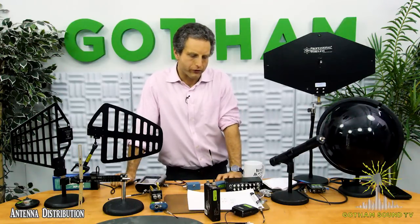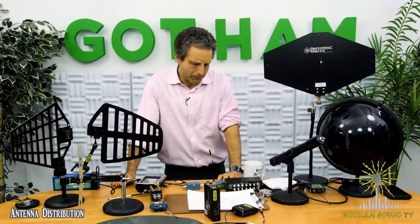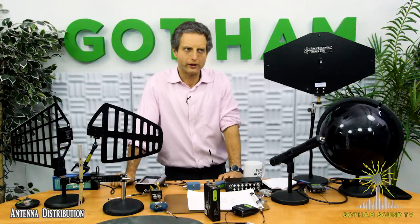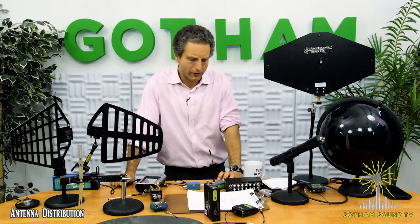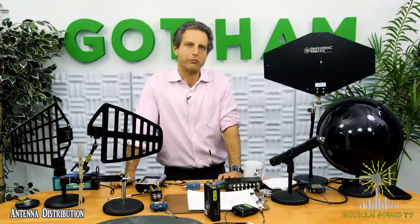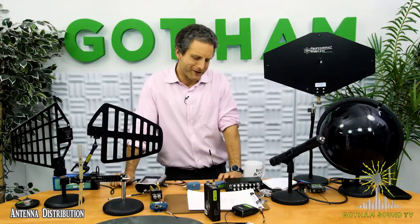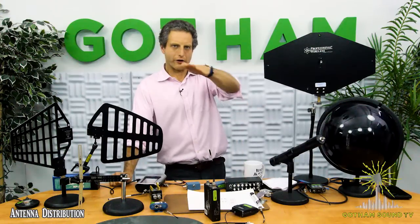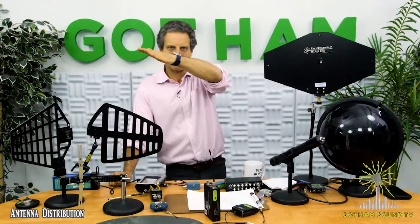And I think that's a good opportunity to talk about the nature of what's going on with RF circuits. RF amplifiers, which are in all of these components we're going to talk about today, all of the active ones, you can think about as a kind of very tweaky mic preamp. If we think about a really good amplifier, the more energy you put into it, the more energy you get out of it, in a perfectly linear fashion. If we were to draw a graph, it would be a straight diagonal line.